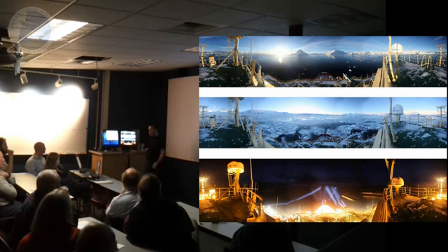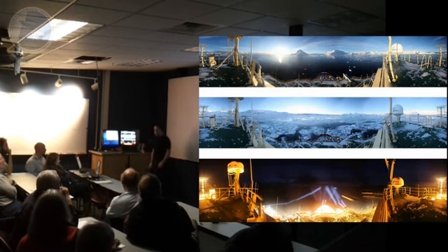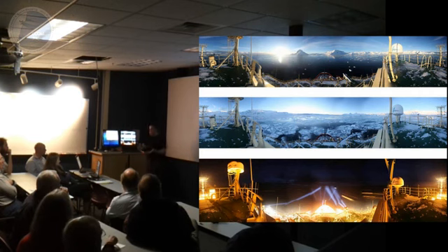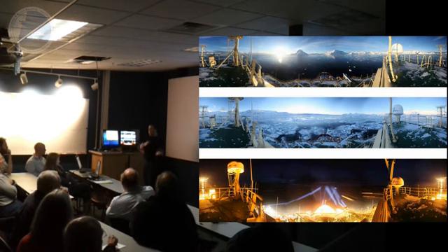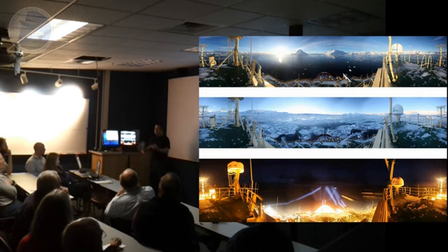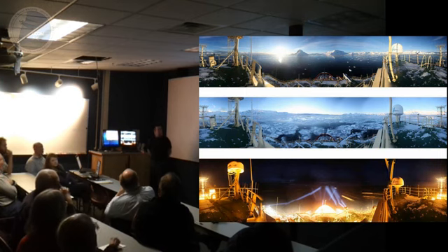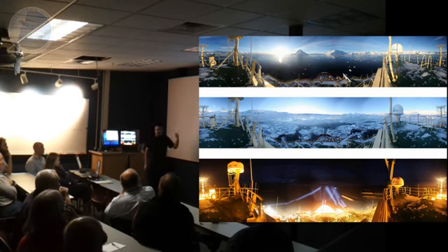What I would do is basically disable the auto gain and start at some baseline number. Then when I would take one series, I would take the average of the values and say, oh, that looks a bit dark, so for the next one, bump it up, and just make sure it stayed within a certain range. That meant the first set of images might be a bit too dark, but then they go into a range which makes sense and hover in there. So it was kind of like adjusting based on what you just saw.